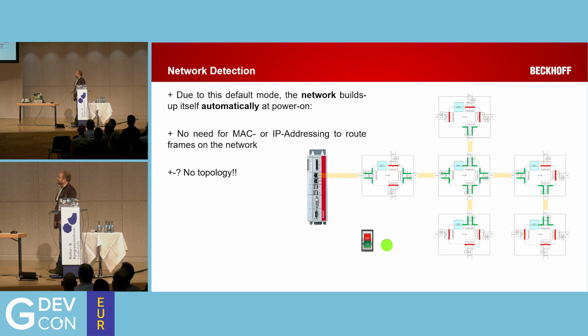If you need the ability to do that, there's a system called Hot Connect, which is part of EtherCAT, which allows it to use an identity header and allows you to move these devices around your network. But it's something you have to think about ahead of time. It's not like other Ethernet-based systems where you can plug them in everywhere because of the network IP addressing.